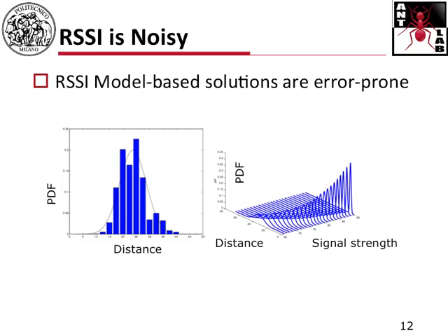Do you have any questions? No questions. Good. And obviously, the shape of this PDF depends also on the level of emitted power, so the level of power the transmitter is actually using to transmit its beacons. The higher the power, the narrower this PDF is; the lower the power, the larger the PDF. Because if the transmitted power is lower, the impact of any interference would be higher on the received signal indicator measure. Clear?